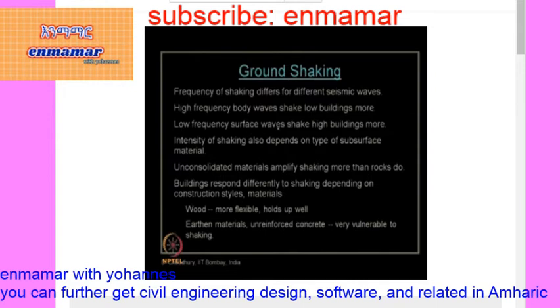Whereas the low frequency surface waves are those seismic waves which travel close to the ground surface, like the Rayleigh wave and Love wave. We will discuss these types of waves in due course of time in this course. If they have a low frequency, it has been found that they typically shake high buildings more, that is high rise buildings, very tall buildings. There are reasons; the technical reason we will give mathematically later during the course of this subject. So this is the typical behavior of the effect of frequency variation of various waves on different types of buildings.